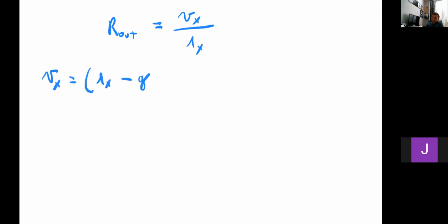So referring to that figure 8.21, the output resistance as seen at that node is our test voltage divided by the current. And again, if we look at the nodal analysis at that node, I can write that Vx is equal to the current minus the current source, and that's going to be GM times the gate to source voltage of the common gate, not biasing because there is no biasing.